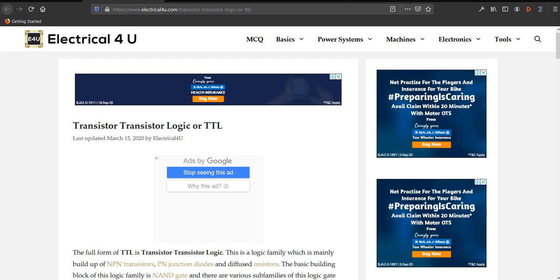No, it will go to 1. No, wait. Here it is 0, and it will go to clear 1, so it will go to 1. And then X is again going back to 1. But then both preset and clear are 1, that means it will continue in the previous state. It will continue to remain 1.